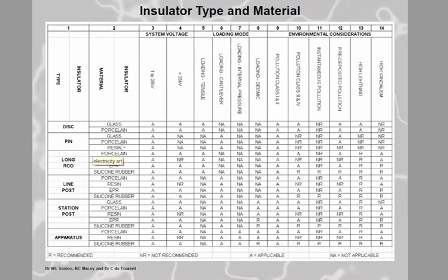It's got in it an ester, which has got a double bonded oxygen. It's prone to hydrolysis. So all your cycloaliphatic will chalk because of those little double bonded oxygens, okay? It will chalk, it will go white. Put your hand over it, it's like PVA paint.